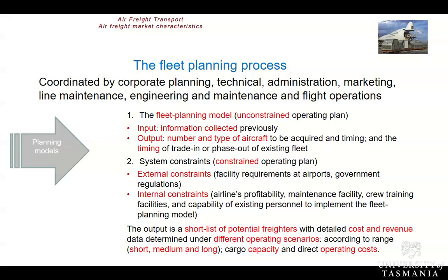At this point in time, so you've gone through that stepping process, you're going to get an output of shortlisted potential freighters with a detailed cost and revenue analysis at your disposal, based on a range of different scenarios. Whether you're going to use them for short, medium or long haul, what the cargo capacities available are, and what the direct operating costs are.